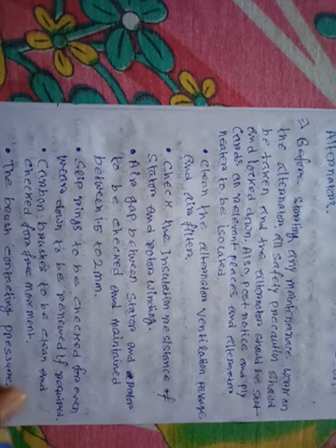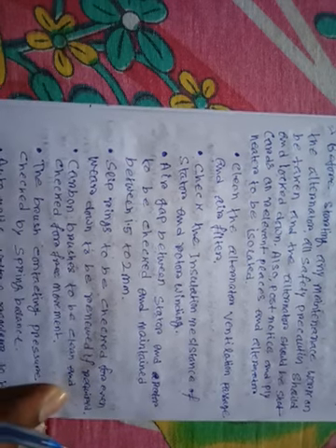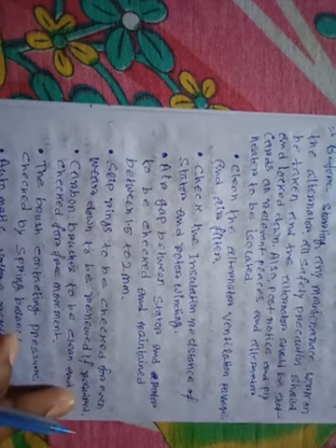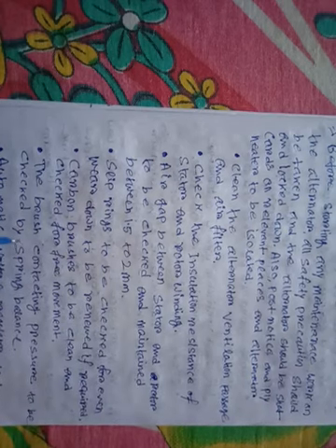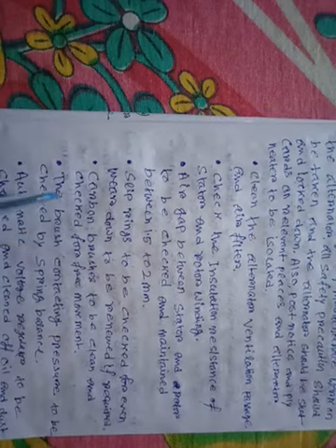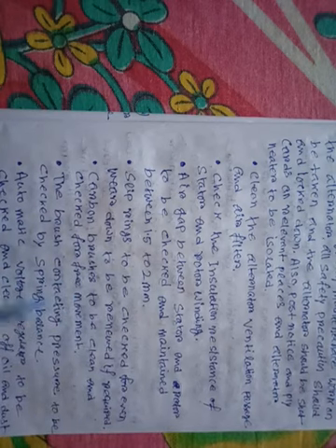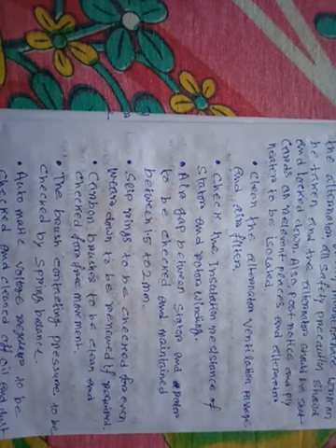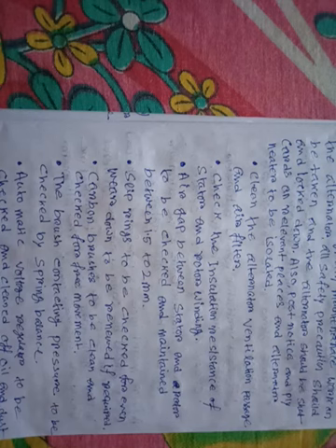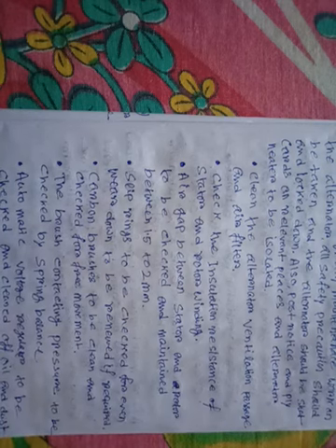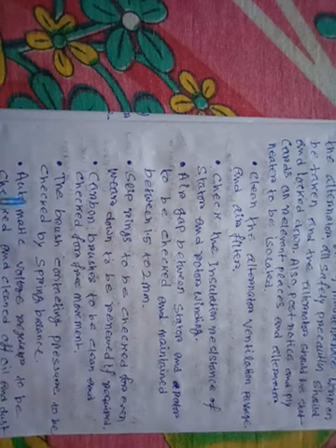Next is slip ring, to be checked for wear and turned down or renewed if required. Next is carbon brush. Carbon brushes are provided to the alternator for collecting the electric power. The carbon brush is to be cleaned and checked for free movement.